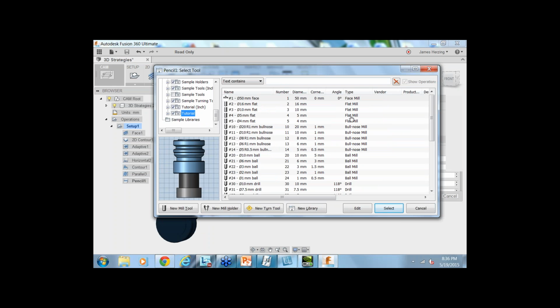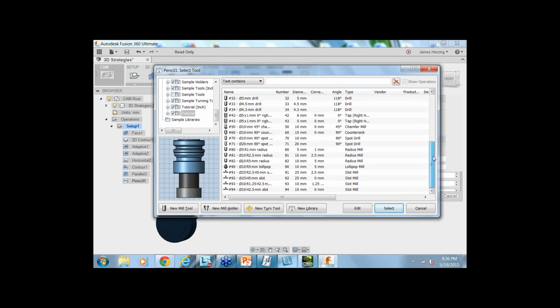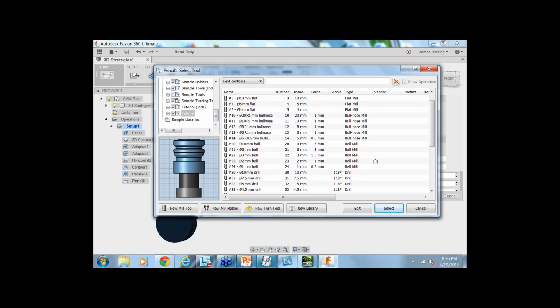So in our tutorials, let's go ahead and scroll down and use the 3mm ball. I guess I scrolled too far. Ooh, what's a lollipop? So question for you guys in the back. Right now we're about to use 3 pencil operations. We're going to use 3mm followed by 2mm followed by 1mm. Is that reasonable because it's changing the tool 3 different times, or does it make more sense to just use the 1 and have it go to town?